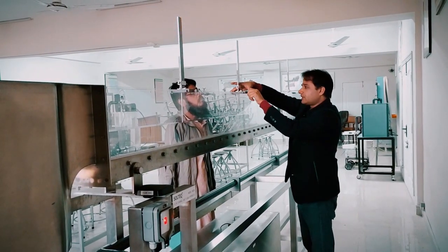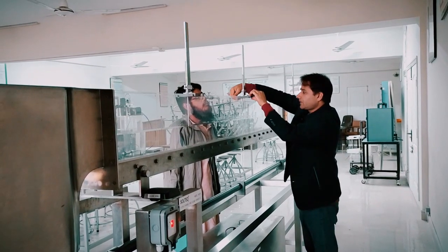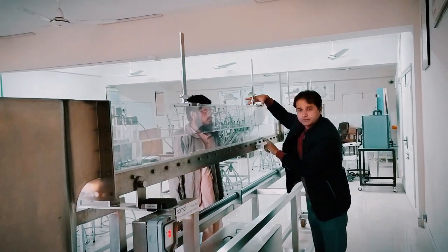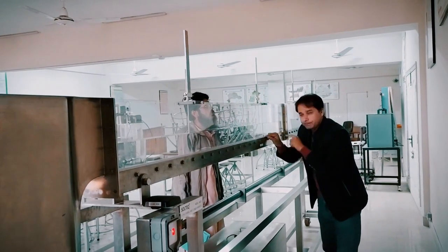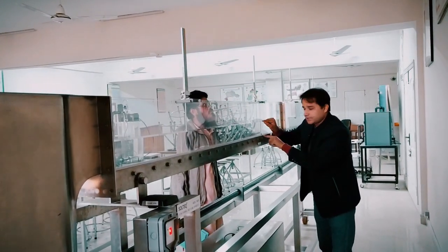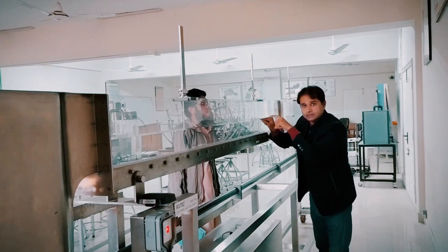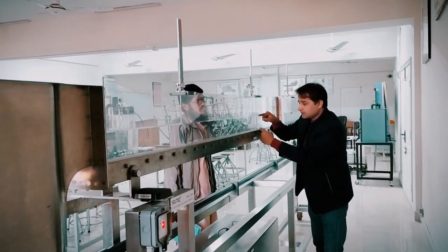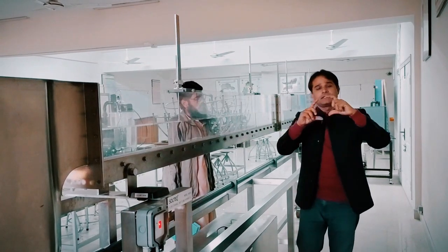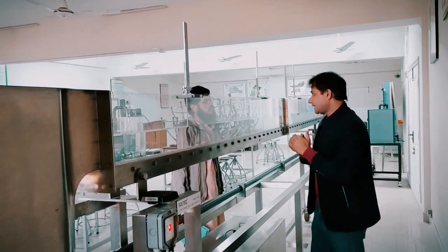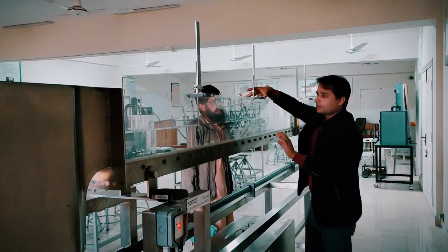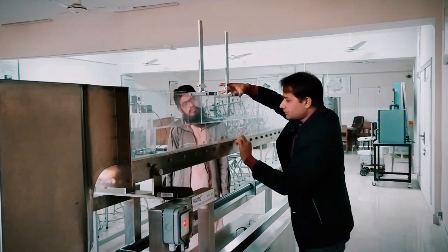The first point is our starting point of the read. At this point, we have to take the reading of the bottom depth, and we have to take the surface water depth. Then we will subtract the bottom depth from the surface depth, and we will gain the flow depth. Again, after taking this depth, we have to measure the water flow depth at section 2.